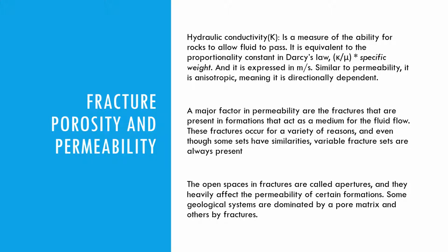Now, here it can kind of seem like hydraulic conductivity is very similar to permeability, but it is a little more than that in the fact that it takes into account the fluid itself that is moving rather than just how permeable a layer is. As you can see, it's taking into account the dynamic viscosity of the fluid and the specific weight.